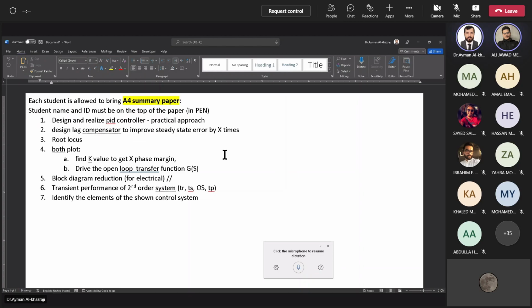Why? In the example of the slide, this is not percentage. It is also times. Yeah, but you multiply by 1/20. 1/20 is the ratio between poles and zeros, and this is different from the error. It is not the error. You divide because you want to find the ratio between pole and zero, right?